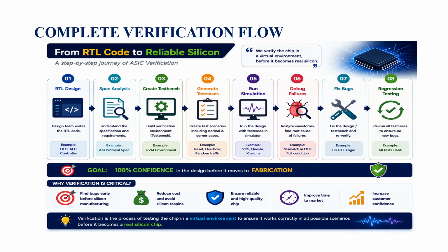In the real-time project process, whenever we are starting verification, we have to create the test plan. What does it mean? In that we will be writing the features supported by the design, and why we need to verify that feature, in a very detailed description.